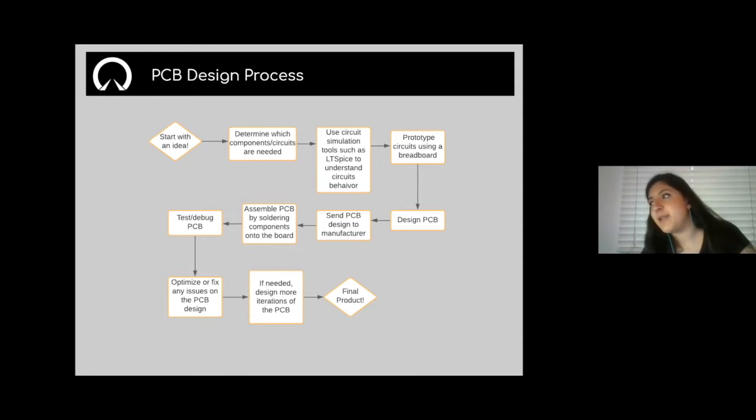The next phase is manufacturing. There's some criteria that we can give you pointers on, and we'll talk about that later in the presentation. After that, you head into assembly and testing. This is the fun part. You solder all your SMDs and through-hole technology. You connect your power supplies, you strip and crimp your wires, and then you check if your design actually works. You optimize and fix things.